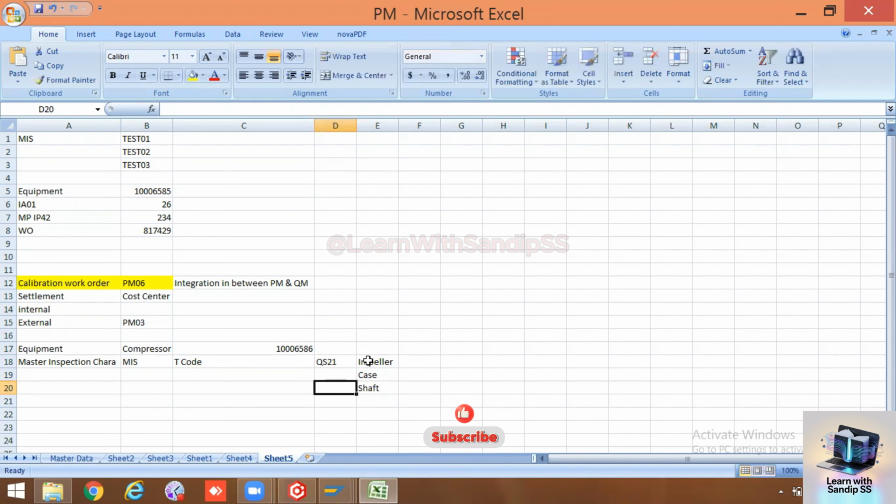It's very random. Basically, the maintenance manual will give you the details on which equipment, what calibration you need to perform, and on which components. These are the parts of the equipment. Pressure gauge, flow meter, compressor pressure do not come under this calibration. You can take the pressure gauge too, but the mandatory prerequisite is that your company should have the facility to calibrate it.